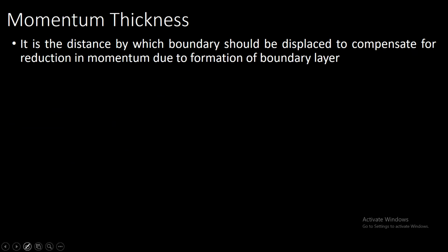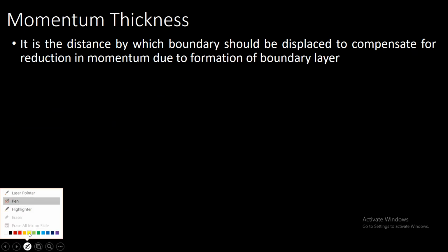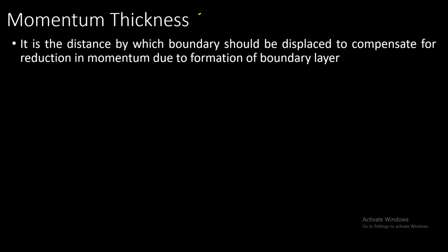Next, we have the concept of momentum thickness. It is similar to the displacement thickness. Momentum thickness is represented as theta. The definition is, it is the distance by which the boundary should be displaced to compensate for the reduction in the momentum due to formation of boundary layer.